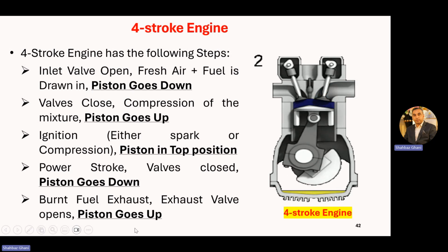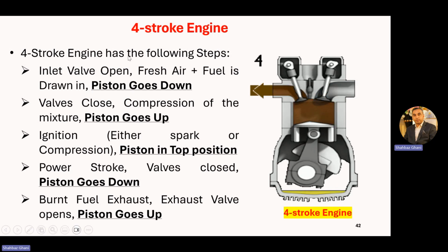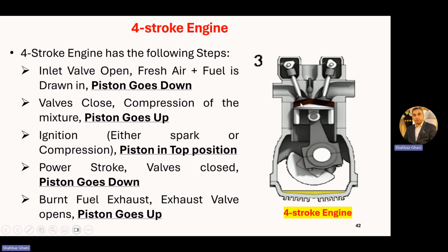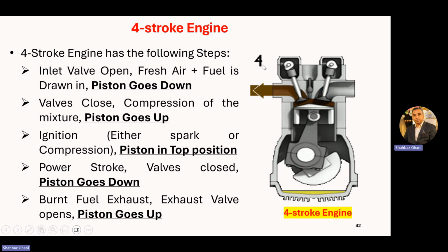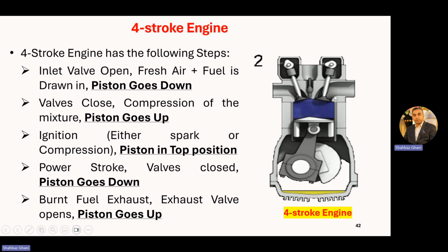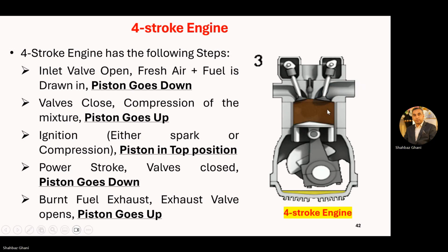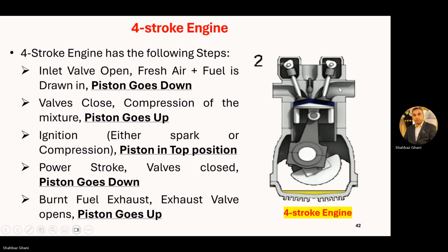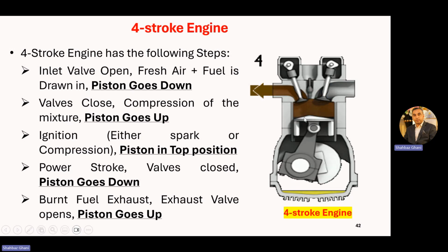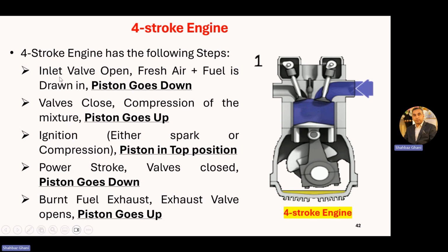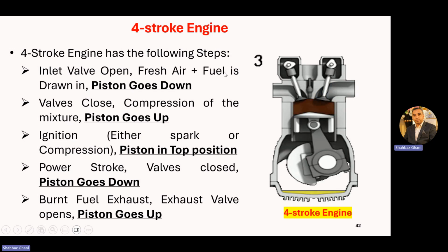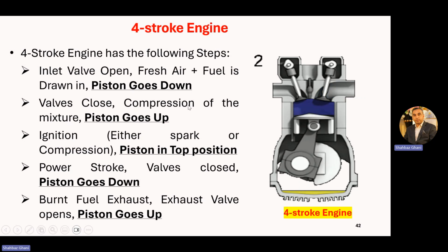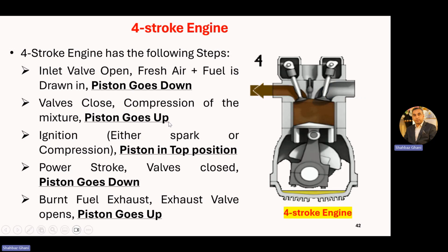Now, a simple illustration. A four-stroke engine has the following: inlet valves open. Stroke one is intake, second is compression, third is power, and four is the exhaust stroke. Inlet valves open, fresh air-fuel mixture drawn in, piston goes down. Valve closes, compression of the mixture, piston goes up.